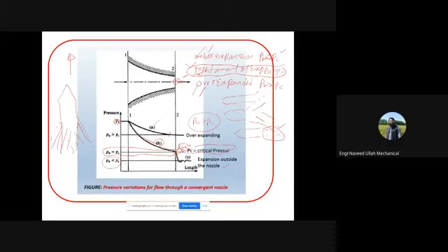When it goes from under expansion to over expansion, on the way you get the right amount of expansion. So just after firing, it gets the right amount of expansion, and this will give you the maximum mass flow in the backward direction, and similarly the maximum velocity of the jet in the rearward direction. And if the mass flow rate and the jet velocity are maximum, then obviously the thrust will be maximum in the upward direction, right. So deliberately the under expansion case is provided here.